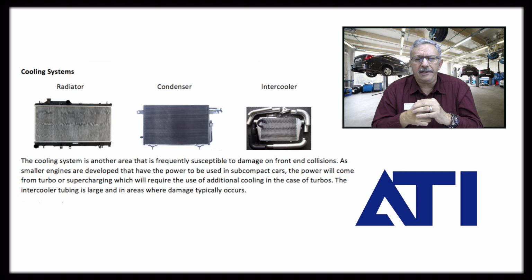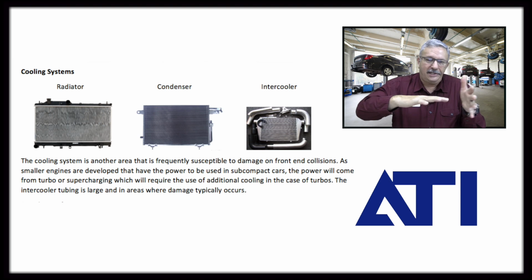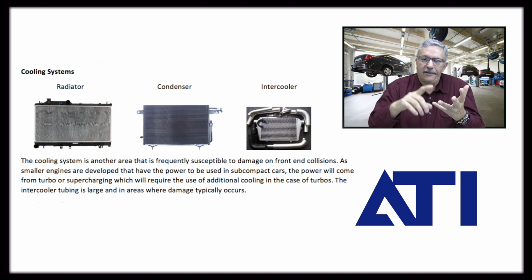The other thing that we would look at is, in the turbocharged cars, you're going to have this intercooler system. And again, you can see from this image, lots of piping. There's going to be lots of connectors. So remember, vehicle hits, comes back, all those things have moved. I've got to check all the clamps, I've got to check all the hoses, got to check all the tubes, piping. All those things have to be visually inspected.